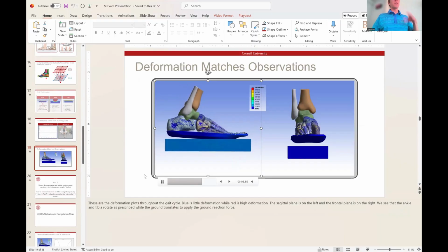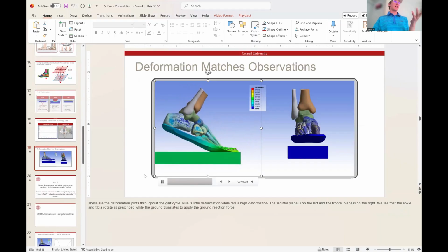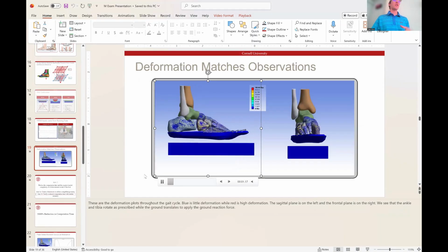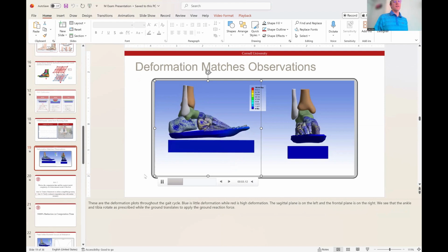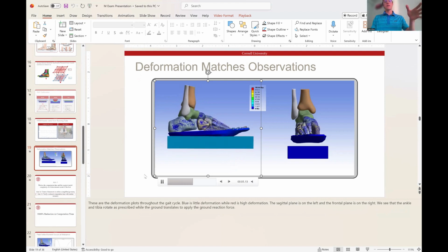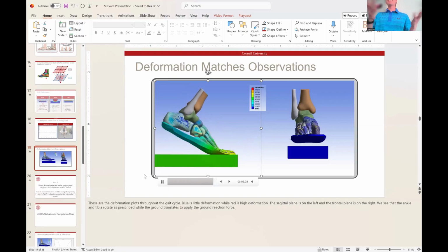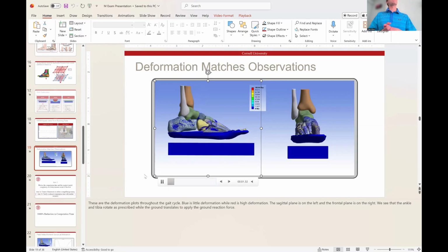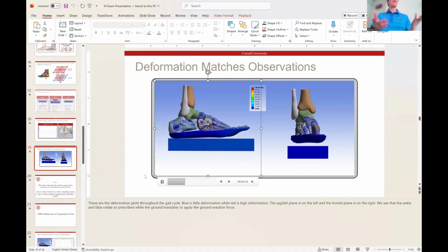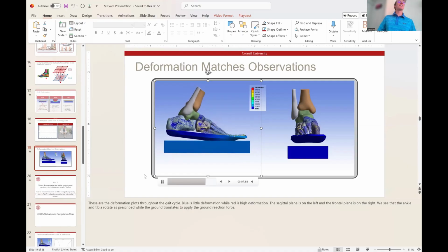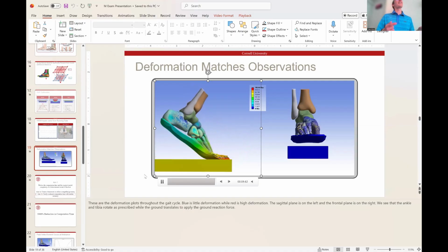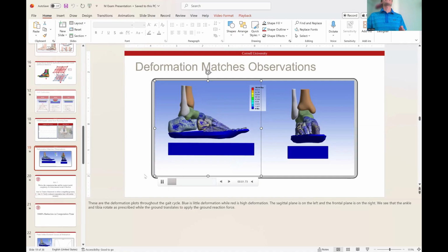These nodes are placed on the surface but not constraining that rigid body, so they're following the rigid body themselves. Because I needed to attach the skin node to the bone node, I had to create the nodes, which ANSYS doesn't let me do on a solid body mesh. So how I did it was I told it, you are contacting the ground now, even though it will never contact the ground.